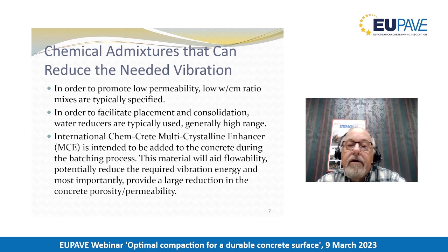There are other products out there that do dual duty. The only one of those that I have worked with in the past several years has been the product that's on the screen, this International Chemcrete Multi-Crystalline Enhancer. Done extensive research with this product, and we found that if it's introduced into the concrete during the batching process, or after the fact, in the case of a transit mixed truck, you can add it on the job site.